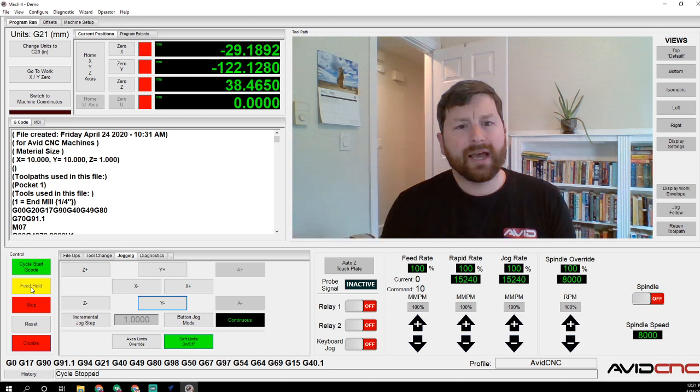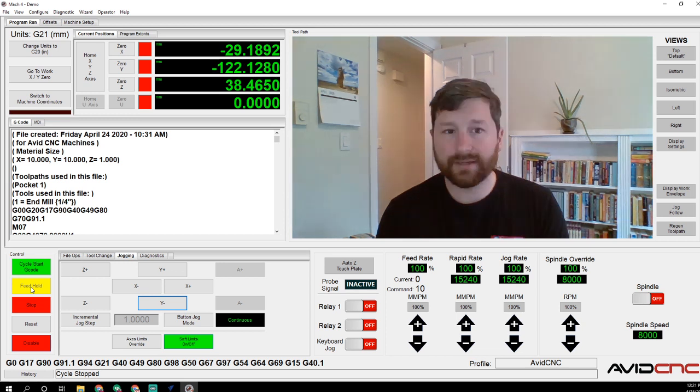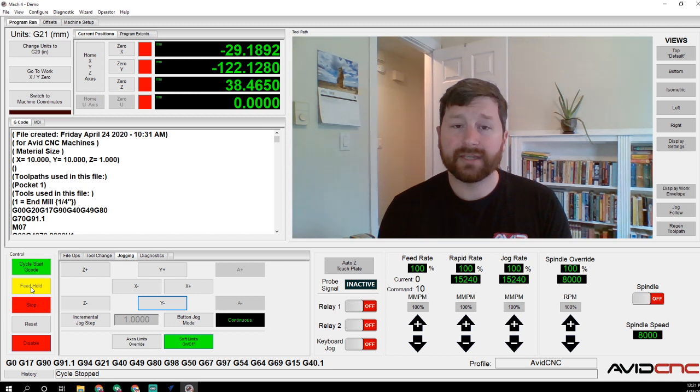Well, I tend to not start G-code in the middle as a practice, because G-code files can be really long, and sometimes you think you're in a different place than you are. So I typically approach this in two ways. I'll go ahead and rehome my machine. I will make sure all of my offsets are still set in the same place that they were when I started, and I'll just start that program over fresh. If it's a short program, I'll be cutting air for that area before I hit my emergency stop, and then once I get to that, it will continue cutting.